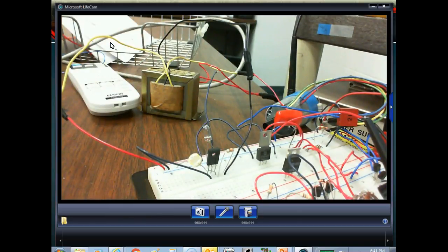I could do the same thing with a bipolar transistor, but the bipolar transistor would be in the active region. When it's in the active region, it's dropping a voltage. And when it drops a voltage and you put a current through a voltage, P is equal to what? V times I, right? So bipolar transistors are great, but when we operate in that active region, we're going to have to sink them a lot.